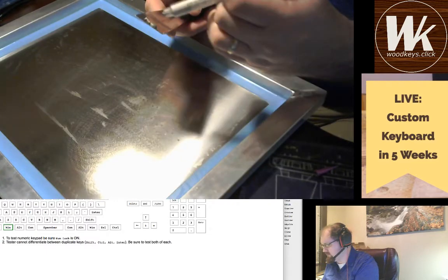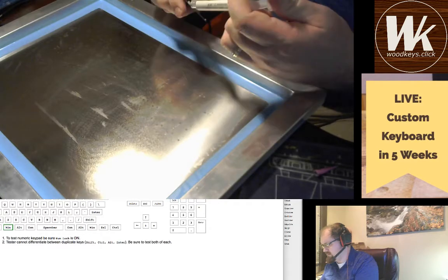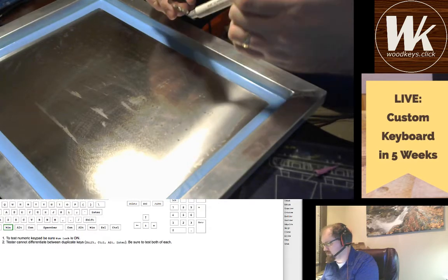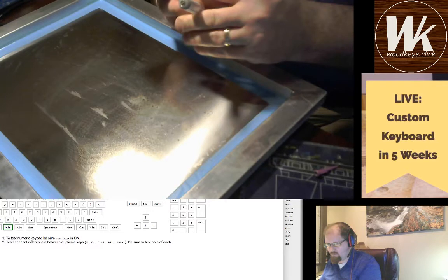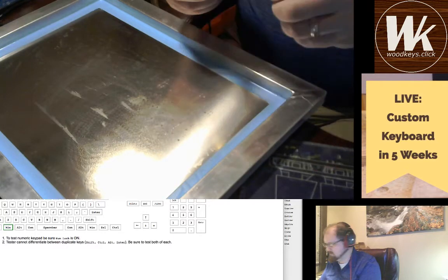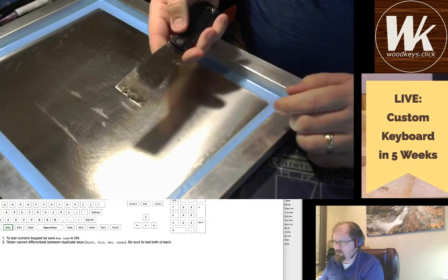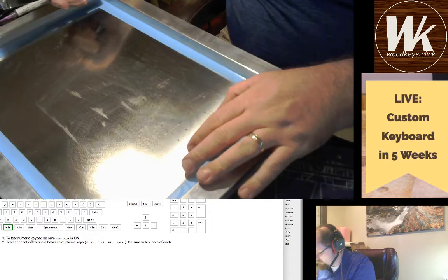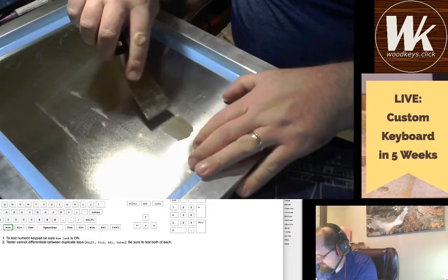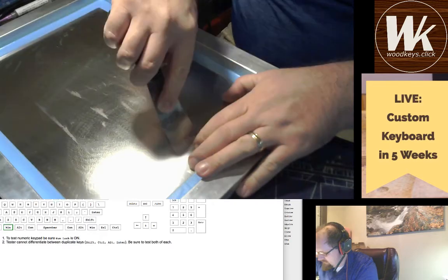That's one thing about these sockets, is that they will suck up a lot of solder paste. So just got me a pretty good goop of it on there, as you can see, and then I'm just going to get to spreading it out. Making sure I fill in all the holes, scrape away the excess.